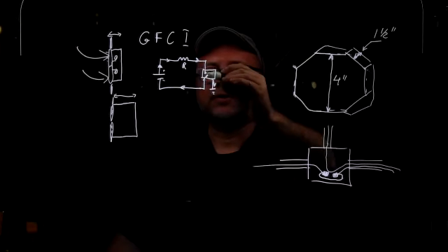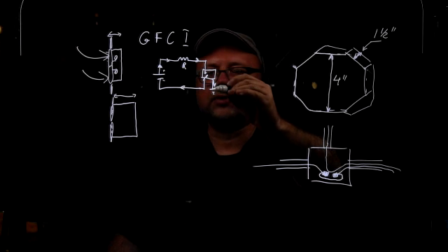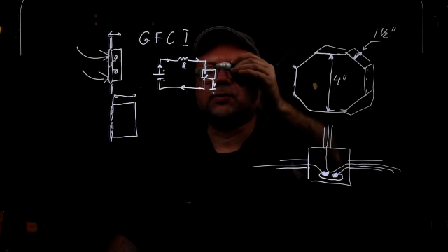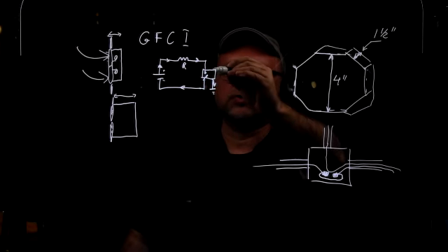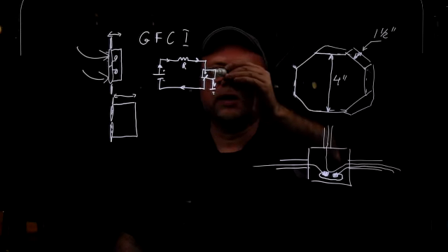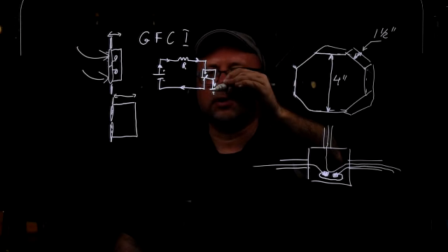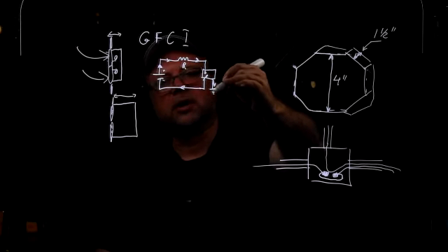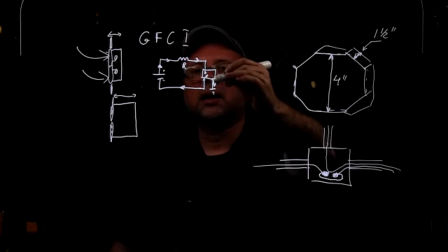Same as if, for example, one of the wires becomes detached by accident and it touches the chassis, the ground is going to take the hit. So when you touch that metal box, the electricity is not going to flow through you to the ground. It's going to have a straight path to the ground. That's why we bond the things, or we ground the chassis.